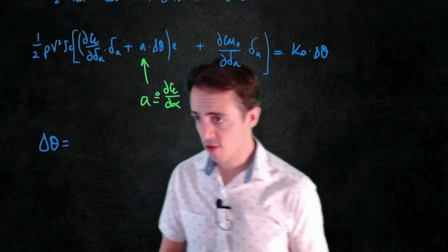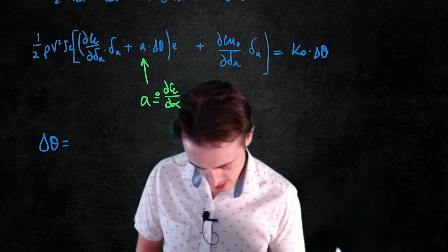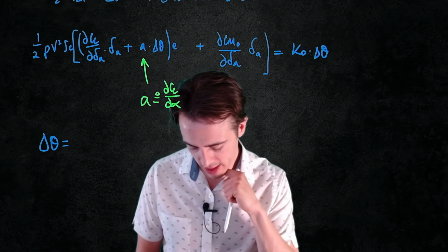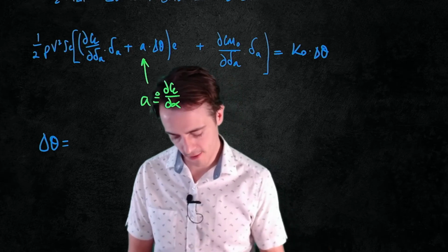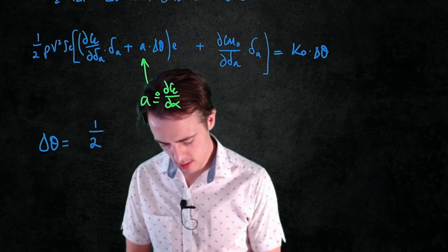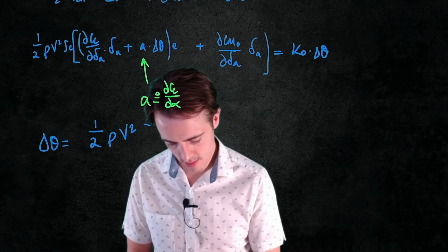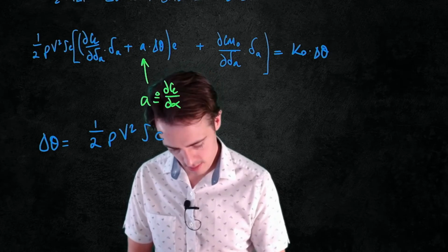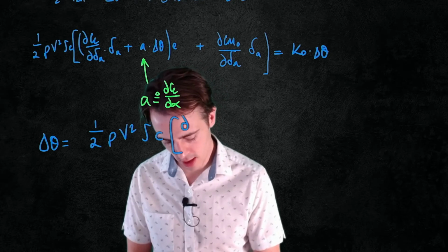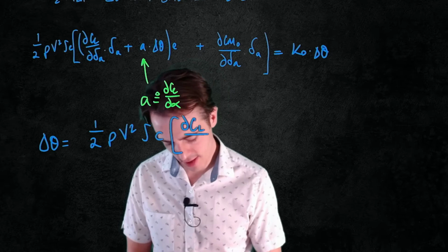I'm just going to copy this from the notes rather than doing the rearrangement here, but we can see there's going to be a KD in the denominator, and it's going to be a fraction. Being careful because I used a horrible Greek letter that I can't reliably draw in the notes, and I'm using delta A for the aileron deflection here.